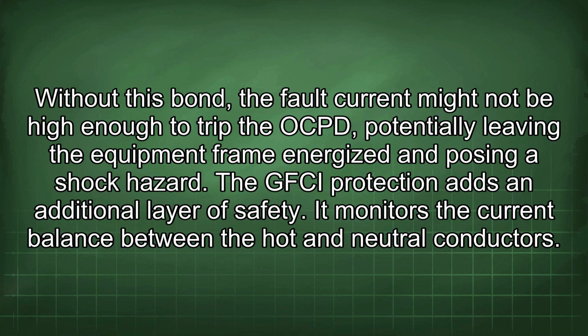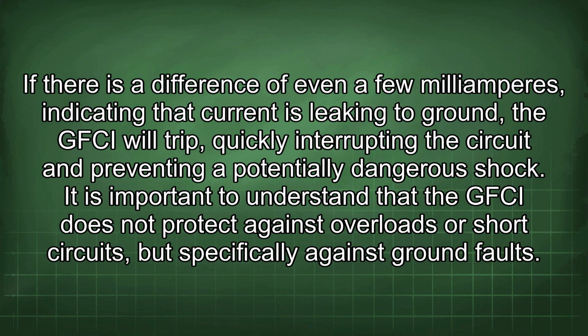The GFCI protection adds an additional layer of safety. It monitors the current balance between the hot and neutral conductors. If there is a difference of even a few milliamperes, indicating that current is leaking to ground, the GFCI will trip, quickly interrupting the circuit and preventing a potentially dangerous shock. It is important to understand that the GFCI does not protect against overloads or short circuits, but specifically against ground faults.